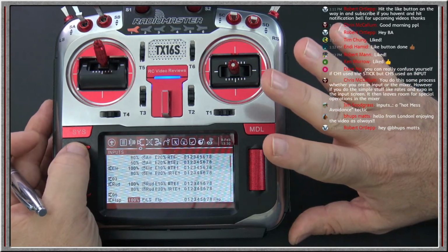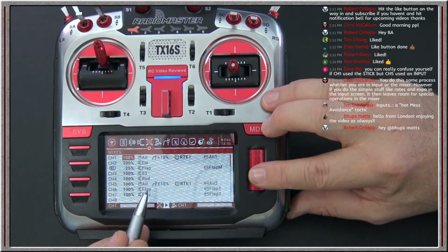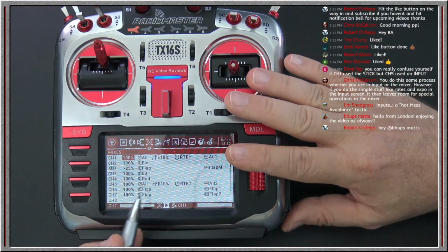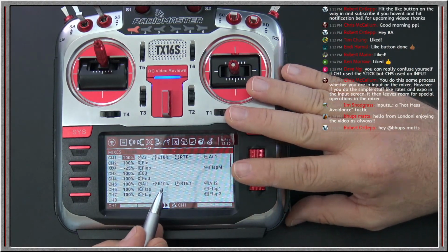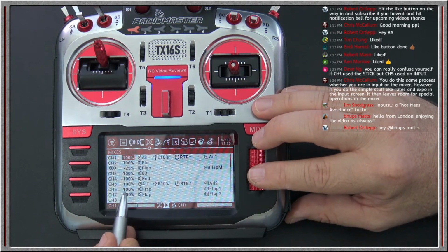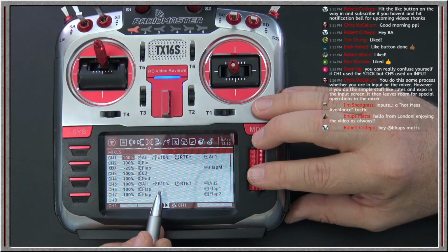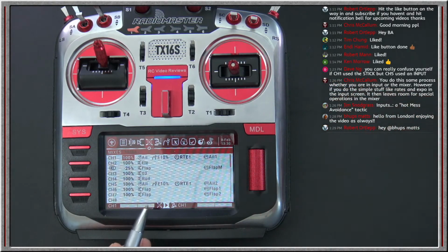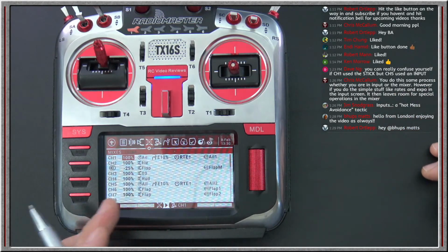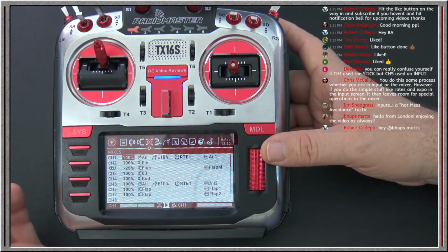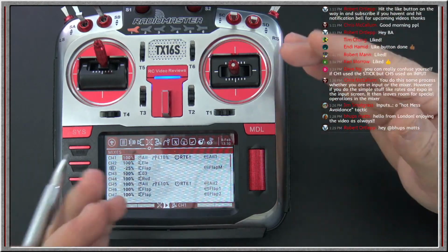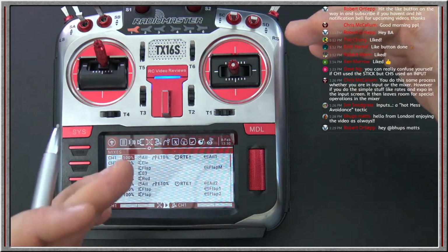Now, in full disclosure, if you assign that same curve to the inputs on both of these, it would also do the same thing. But just remember, you have to make sure that these two control surfaces, both of these flap channels, have the same curve applied. If they don't have the same curve applied, you'll wind up asymmetrical. Okay? Now, that's inputs and mixes. That's pretty much the best example that I can give you guys on why you separate things out and why you use inputs and mixes.